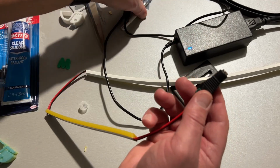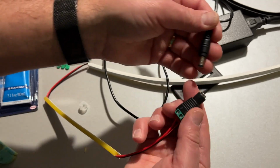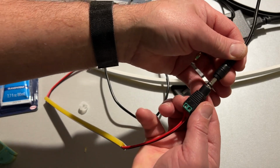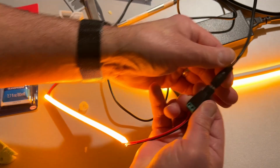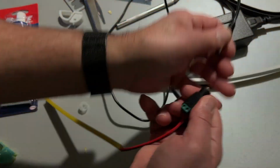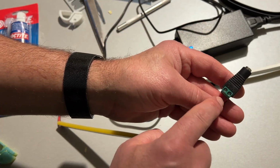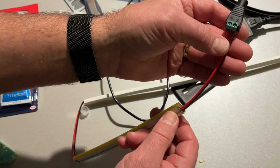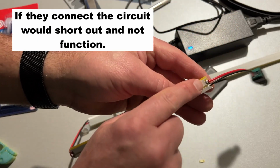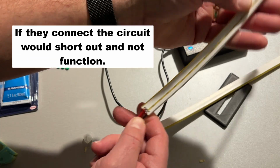Power brick powered on. Of course, this cool piece came with the power brick. I'll have a link to that in the description as well. And when we put it together, bang, we've got bright LEDs. How cool is that? If it doesn't work, first thing I would test is swapping the wires to see if maybe these were the opposite way. And then I would also make sure you did not have any bridges between where you soldered those parts together.